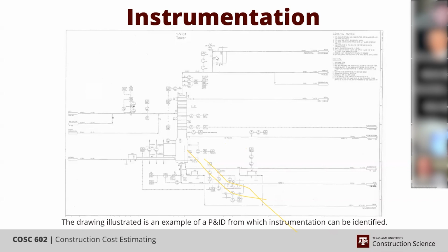One that I did not mention in that list earlier, but you can see in this drawing here, it's hard to read, but it's a PSV. It's a pressure safety valve. So this line right here has a valve on it that if the pressure of whatever's in it exceeds the capacity of the system, it's going to fail by design and release the pressure. And there are 2 types. One type is that once it fails, it has to be trashed. And another one, when it fails, it can be reset and reused.